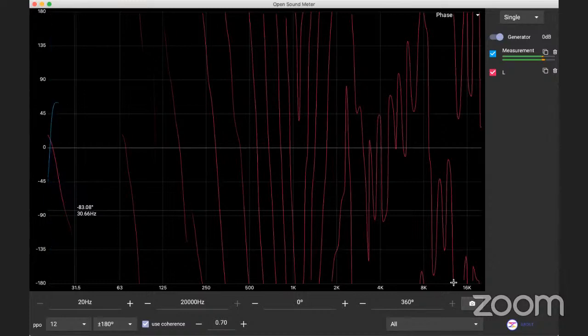You can use softwares like Ease Focus, and there's another software called Ease, which is a simulation software which a lot of acousticians use to simulate what is happening inside a room. Okay. I assume these are proprietary softwares? Proprietary softwares. Okay. Ease Focus is made by AFMG, which is free of cost. The problem with Ease Focus is that it does not take into consideration walls and ceilings. So you won't get a very accurate SPL measurement, or reflections of a wall, but it does the job to a great extent.